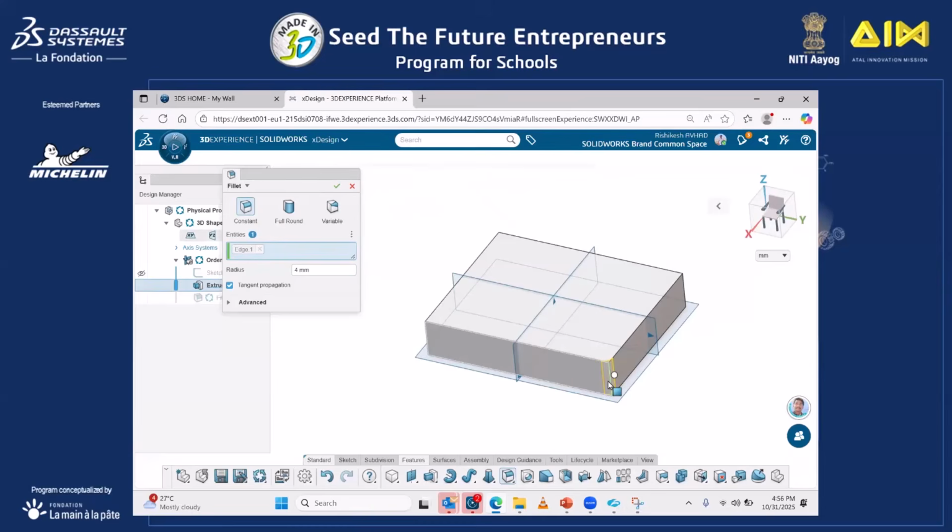If you have seen in your schools, the bench edge is sharp. After upgradation, they provide a fillet, which helps students so that they will not get any injury there. So this is the bench part we can imagine. So I'll give a radius of 10 mm. Okay.